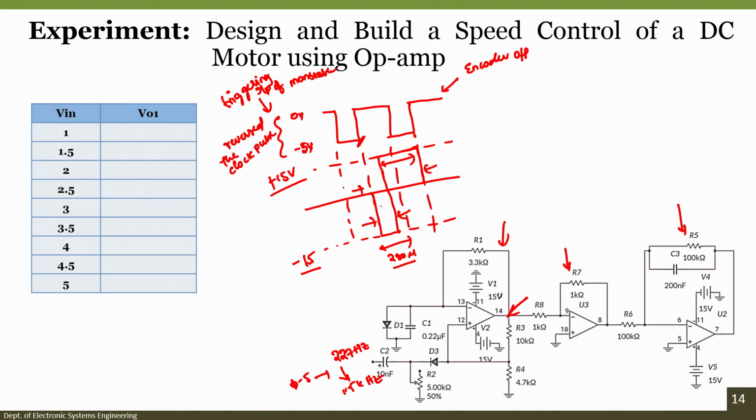But if you see, during the negative cycle the output is very small. So, what we have done is pass it through an inverting amplifier, where the output will have a phase shift of 180 degrees of this particular signal that we have seen. So, finally, we get a signal like this. Whenever there is a negative triggering pulse, this particular width will be 280 microseconds, and this will be based upon the previous state and the next triggering cycle that we get, right. So, this will be the output of an inverting amplifier.